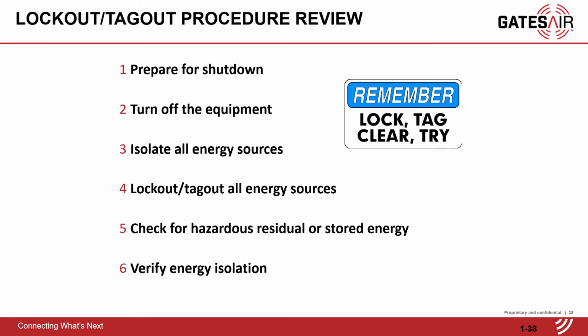So to review the procedure for lockout-tagout, prepare for shutdown. Turn off the equipment and isolate the energy sources. Lock out and tag out those energy sources. Check for residual energy and verify energy isolation.